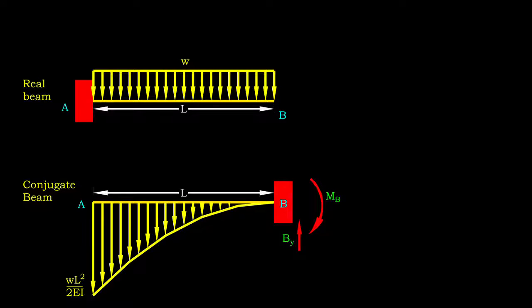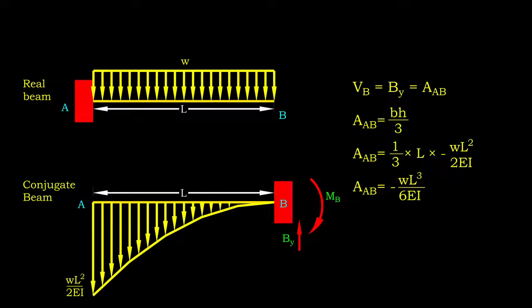At this point, we have developed our conjugate beam. It is time for the action. Shear force developed in the fixed end of conjugate beam equals to the total load applied. Since the internal moment function is quadratic, we know we are dealing with a parabolic spandrel. In this case, the total load applied equals to the area under the distributed load, which also equals to 1/3 of beam length times the peak intensity of the distributed load.